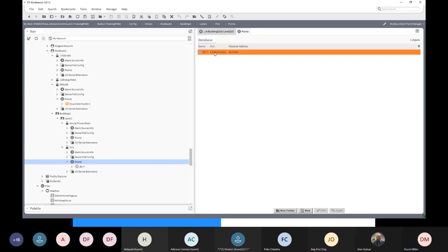So if you have a Modbus project where you're integrating Modbus devices, the first thing you ask for is the register map, the Modbus mapping table or the Modbus register map, and you chase that and you chase it and you chase it, and you make sure you have it in your hand before you start doing anything, because without that table you can't do anything.